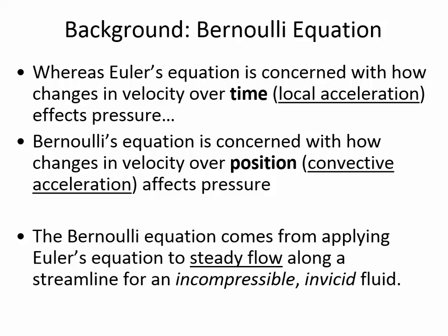So along a streamline means that you can't accurately apply Bernoulli's equation and use this as location 1 and then this as location 2, because they're on different streamlines. And so one of the best ways that we can make sure that we're doing it the right way is just use Bernoulli's equation at the center of a pipe, because then that's on the same streamline. And it's easy to measure the elevation of the center line of the pipe, because if there's an expansion, then the elevation isn't changing. And so it also has sort of a simplifying effect in some of the problems that we solve. But that's what we mean by along a streamline.